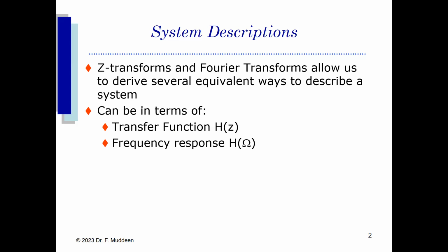Its frequency response, which is a function of capital omega because it's discrete time. So this is really the DFT of it. The pole zero arrangement, which is something that you would have known from your controls way back. But in the discrete time case, remember the relationship of the poles and zeros, especially the poles, to stability: for something to be stable, the poles have to be inside the unit circle.